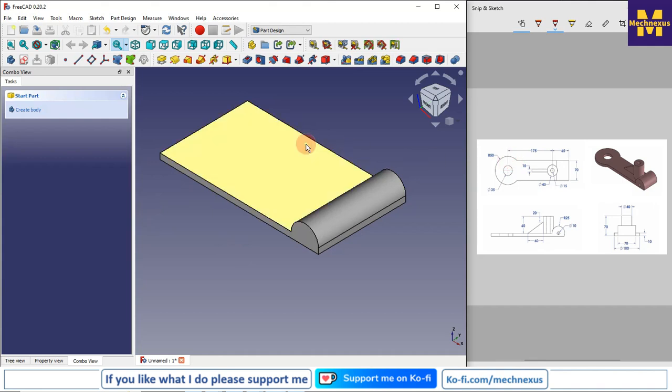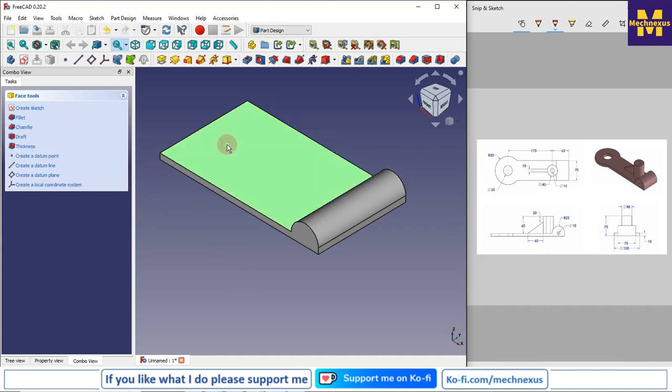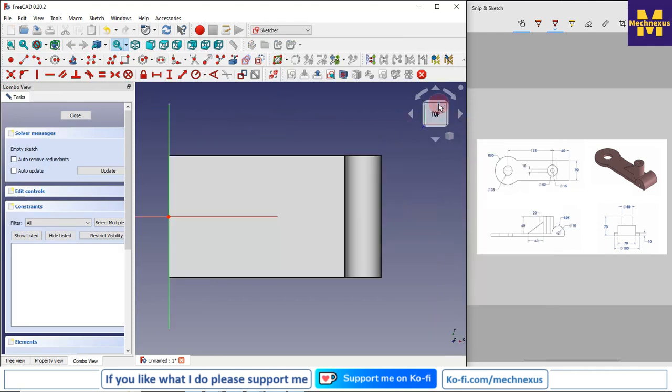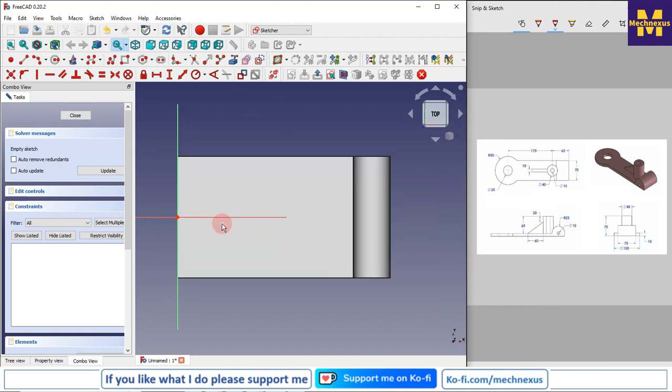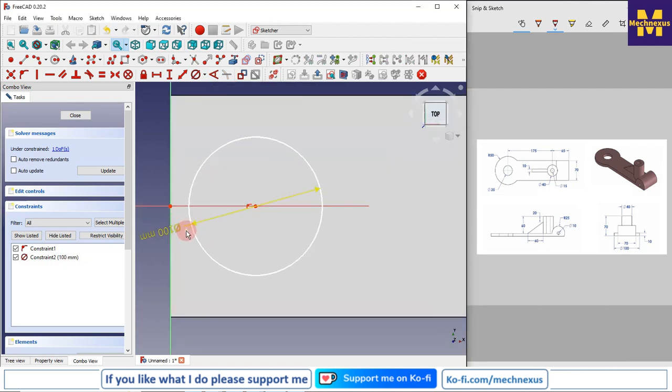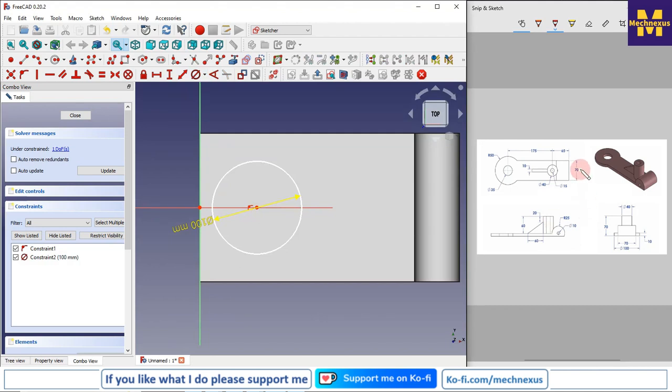And now on this face we will remove the material. So I will create a sketch, and I will set the isometric view. And now I will draw a circle whose diameter would be 100. So I will give it diameter 100, and this is a 70.